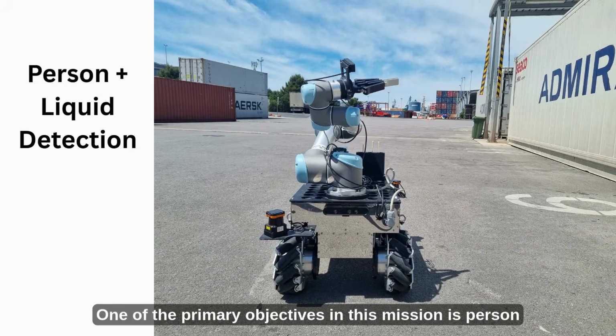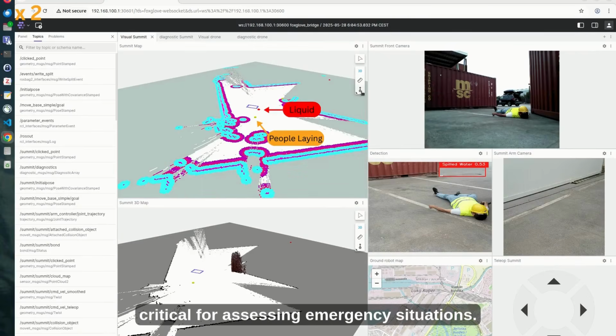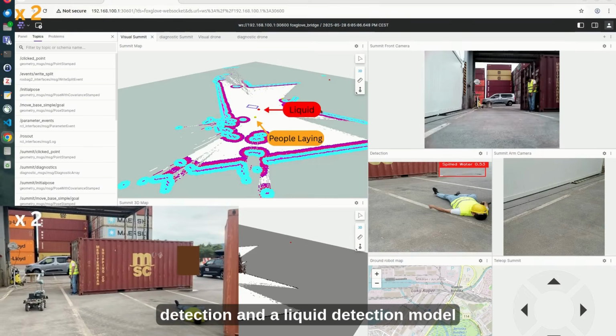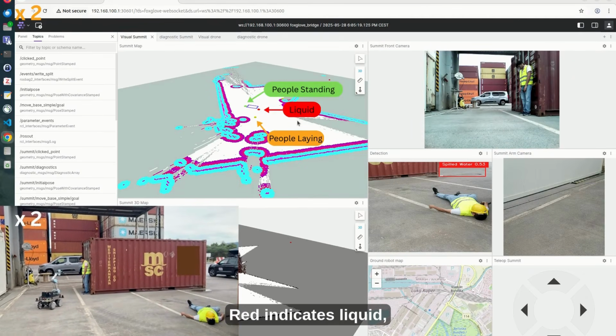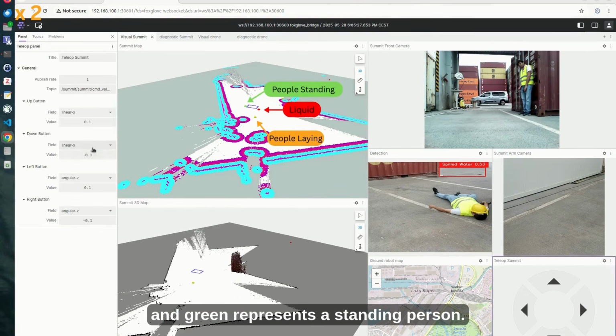One of the primary objectives in this mission is person and liquid detection, critical for assessing emergency situations. We use tiny YOLO V4 for real-time person detection and a liquid detection model to identify potential spills. Detected elements are marked directly on the map. Red indicates liquid, yellow marks a laying person, and green represents a standing person.